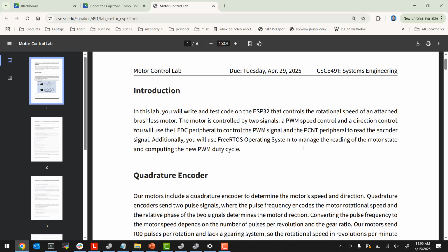In fact, I don't think we can do that, actually, because I don't know if our hardware supports that anyway. That's what I did when I first did this. I did 400 pulses per revolution by doing exactly that. But how did the PCNT XOR? I did it in software. I used 2 channels of the PCNT, counting pulses off the 2 different channels, and then I just added the counts. Oh, okay, that's another way to do it. PCNT counted rising and falling edges, so 200 per thing.